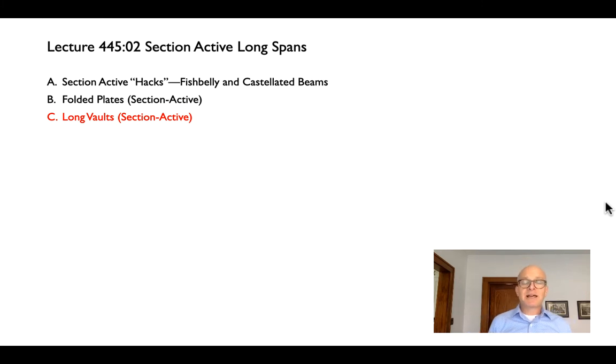Okay, in the next video, we'll talk about what happens when folded plates are curved instead of just folded. And even though the principles are all the same, we're going to make a couple of fine distinctions between what we call short vaults, which are actually not folded plates, but instead are form-active structures, and true long vaults, which are basically folded plates on a curve that function in the same way, right? Separating tension and compression in a spanning element, but doing it along a curved surface instead of a folded one.